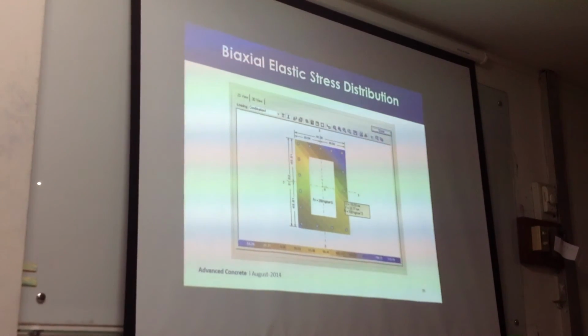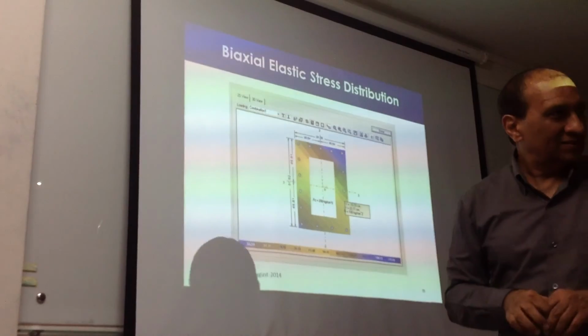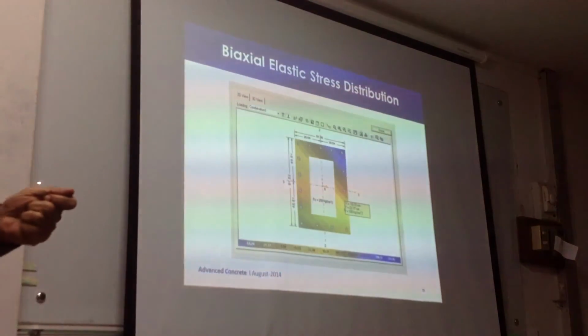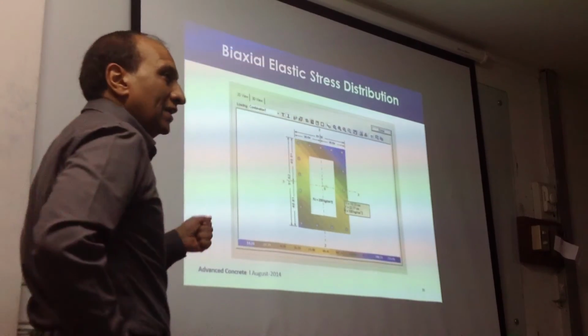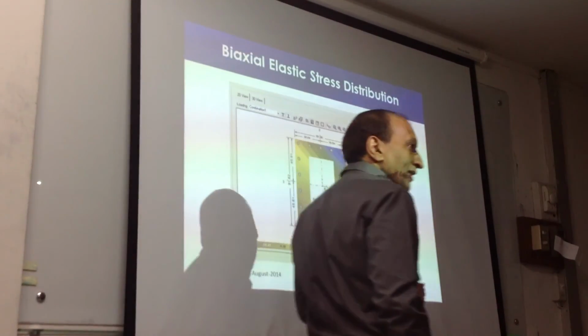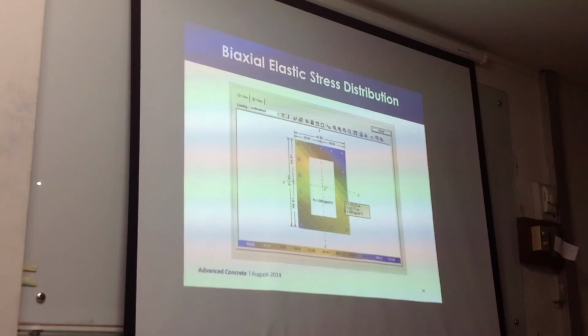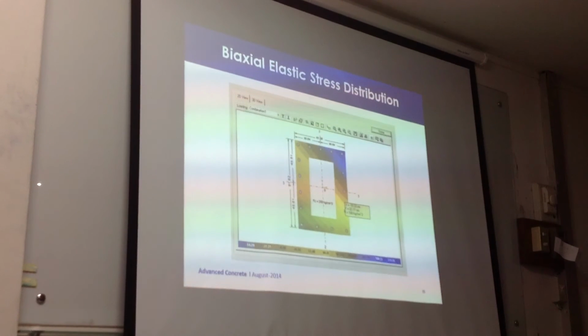Because the cross section limit is 0.003, but you are calculating a strain which is 0.02, which cannot exist. So the elastic stress calculation based on the loading alone is not reliable, has no meaning to us, because it does not consider the material behavior, which may not support that stress strain value.